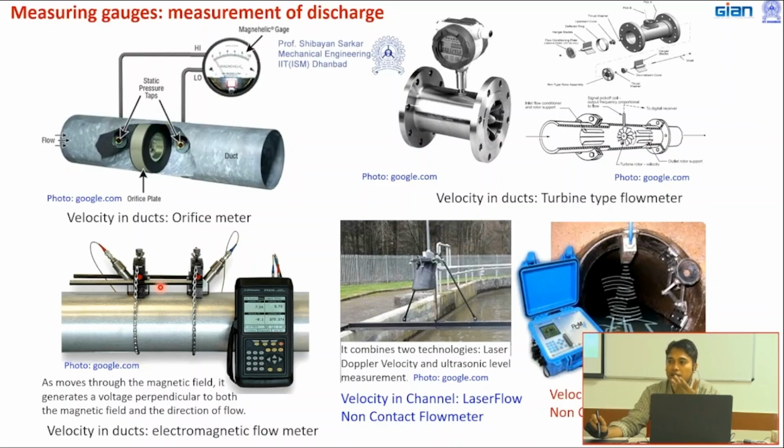for medical reasons people do the ultrasound test. There also some gel is put and then the probe is placed. A similar type of exercise you have to do here. Then the pulse will be passed, another will be received, and ultimately it will give you the velocity passing through the pipeline. Basically, suspended particles carried by the fluid give that reflection, so through this you will be able to measure it.